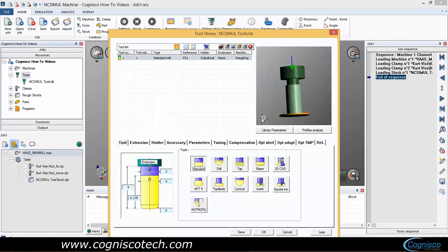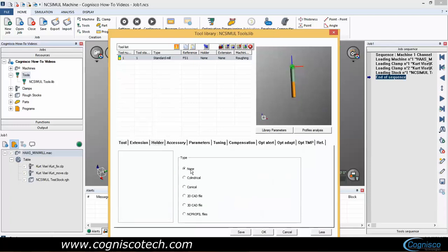So going back to this tool, let's put a 1/2 inch mill. And we're going to change this. Maybe this will be 2 inches. And you see we have a holder. So if I go to my holder tab, we could start without a holder or add either the cylindrical or conical ones that we have already as defaults. And I can change my values here. Let's put this like here, like that. And have a different type of look